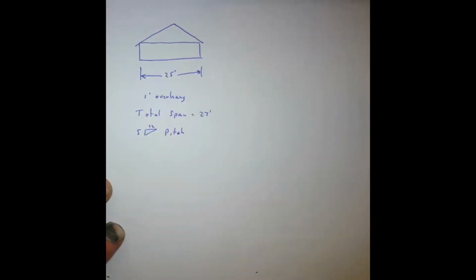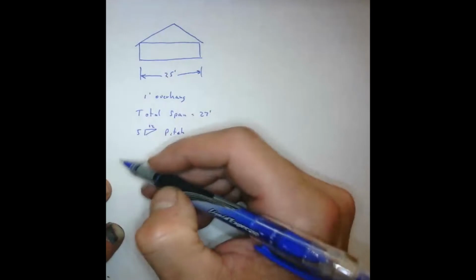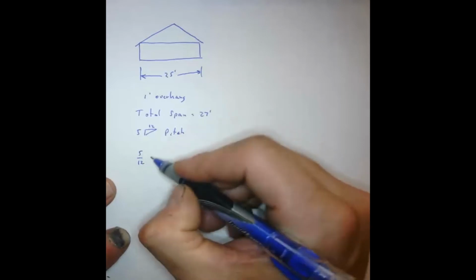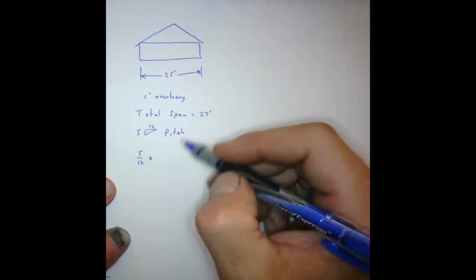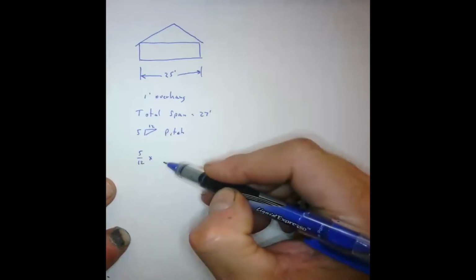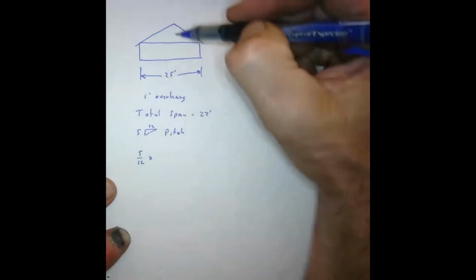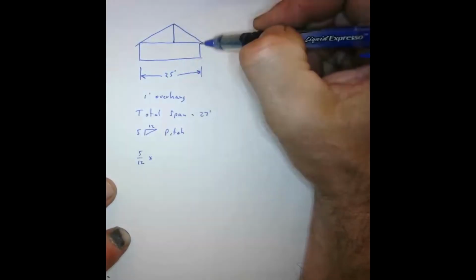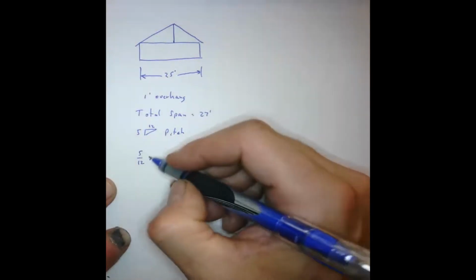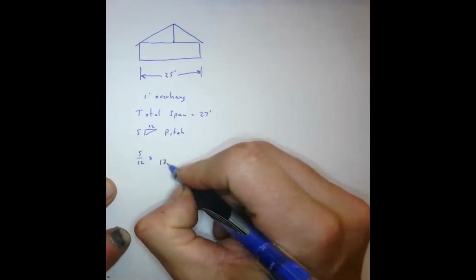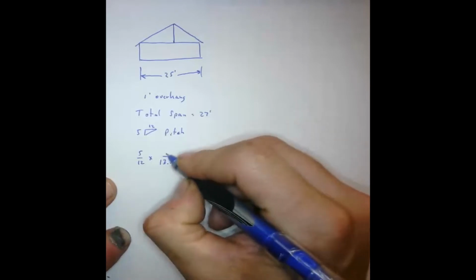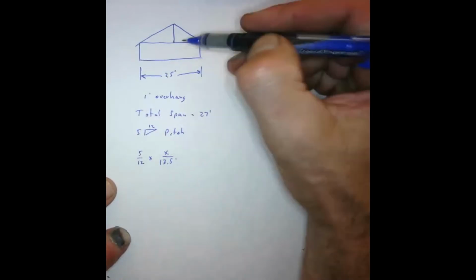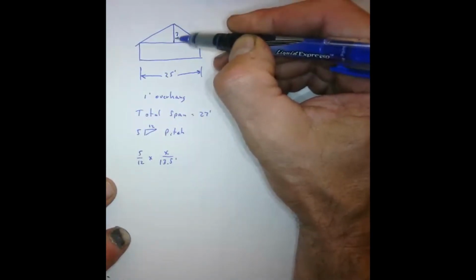And so in order to do this, what we have to do is set up a proportion. So I'm going to do this, 5 over 12. This is the rise, that's the run, and we're going to cross multiply it with, well, we know that our run for our house is 27. But realistically, it's not 27. It's actually going to be half that, because we're only going up halfway and then we're coming back down. So if we take 27 divided in half, you're going to get 13.5 feet, and that's going to be over an x. So x is what we're trying to find, is what is the rise, because that's in question right now.